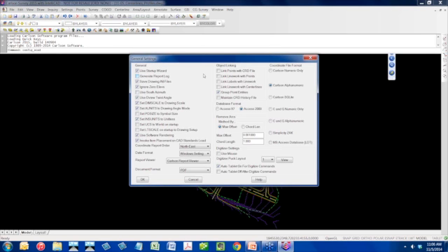But depending on what platform, the number of options you have here has been different. So with 2015 IntelliCAD, we actually have all the same options now that we have for running on top of AutoCAD. If you are running Carlson 2014 with IntelliCAD or earlier than 2014, the only two options here are Group Point Entities and Maintain CRD History File.